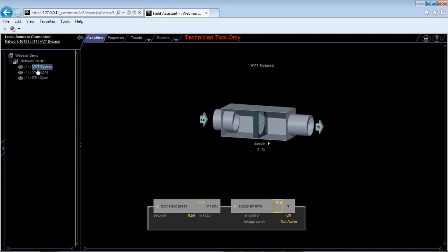Now for the rooftop address, the address just has to be somewhere outside of that zone. Outside of that sequence of zone addresses. So let's say that I had the 5 zones going from 15 to 10. I could not have my rooftop controller addressed in between that 15 and 10. It has to be somewhere outside of it. Doesn't matter where, it just has to be somewhere outside of that zone, that sequence. Make sense?